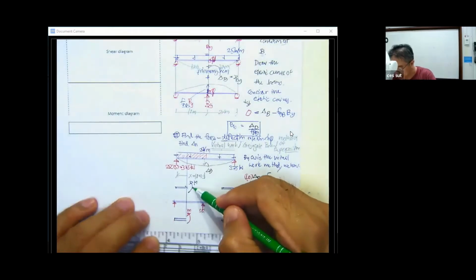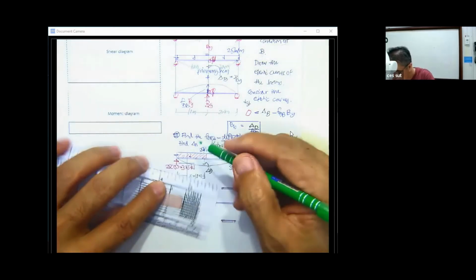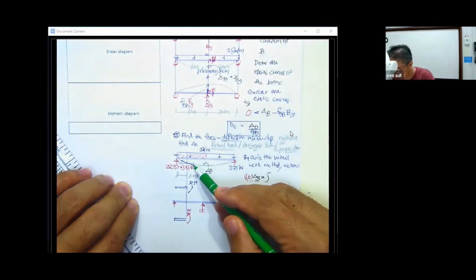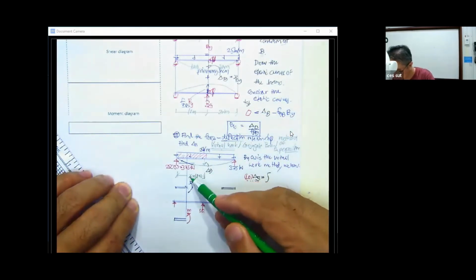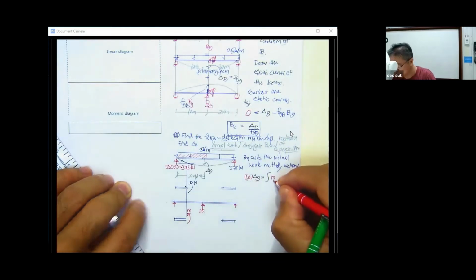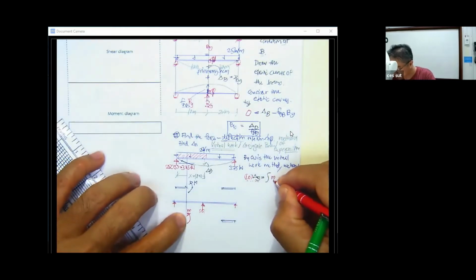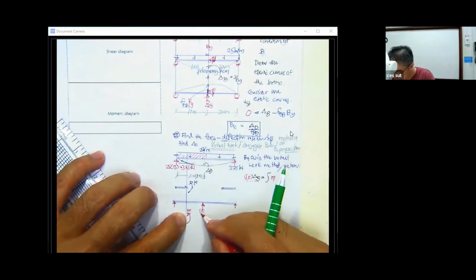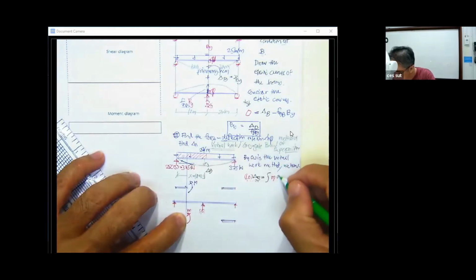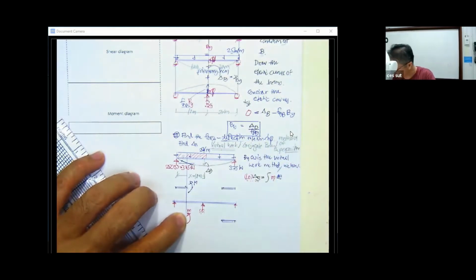This moment capital M causes the deflection of this beam, and the deflection, the change over here, changes with the position of x. So we have this as the internal virtual work, because this is the moment due to the virtual 1.0 unit load, and the change is going to be d theta, and then this is going to be equal to the integration of what?